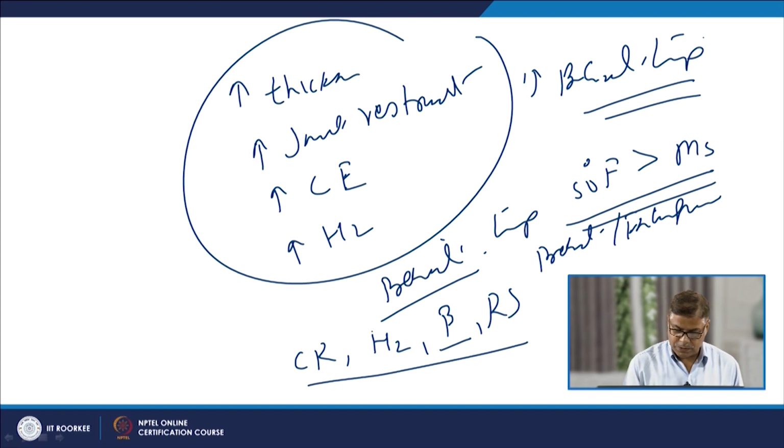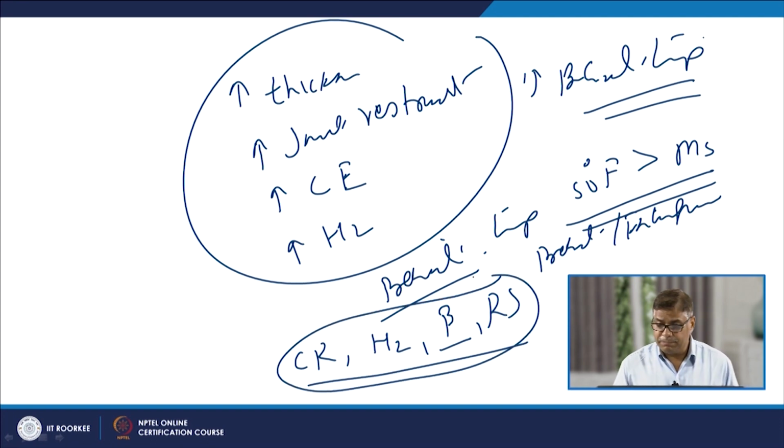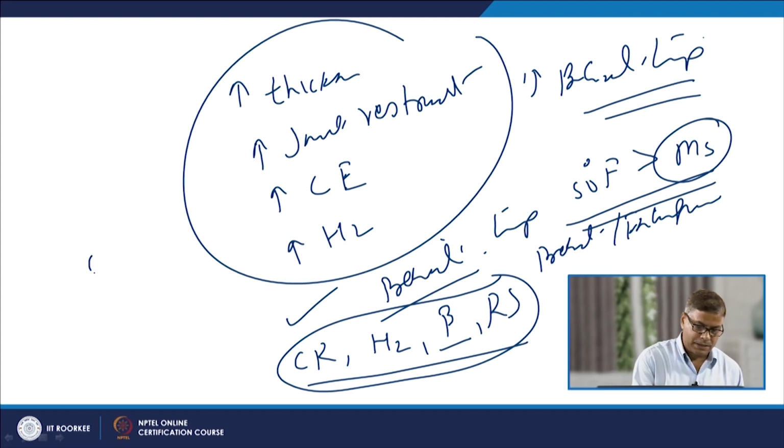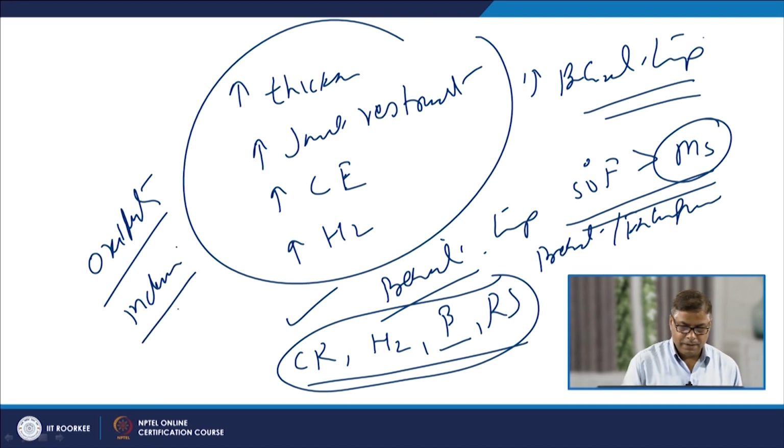So, the preheat about 50 degrees Fahrenheit greater than the MS temperature, or martensite start formation temperature, will lead to all the favorable benefits. However, there is another adverse effect related to the higher preheat: oxidation will lead to the formation of inclusions in the weld as a discontinuity, and dealing with the hot plates will make the job of welding difficult for the welder.